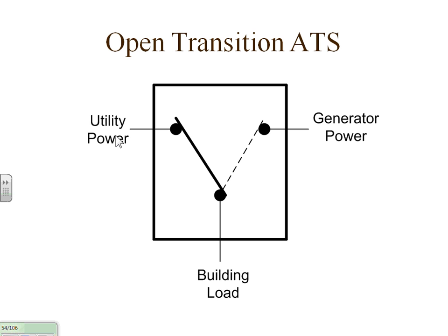When power comes back for the utility, if you think about it, now, even though everybody turned their air conditioners on at different times throughout the day because they were hot, now the utility has to deal with nobody turned them off. So now the utility, when it comes back online, has to start everybody in the world's air conditioner at the same time. So they're going to see a heck of a spike. Very real situation, and it happens. So you might see the utility come back for a second, and boom, especially if it's a hot day, go right back down again, and that's why.